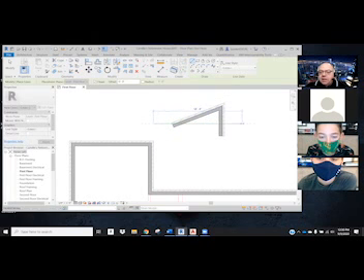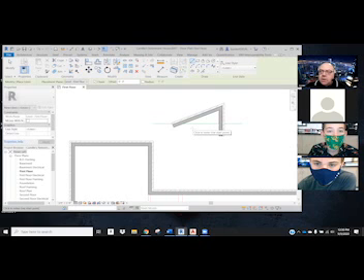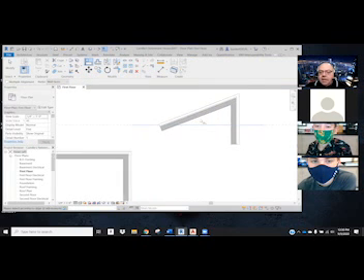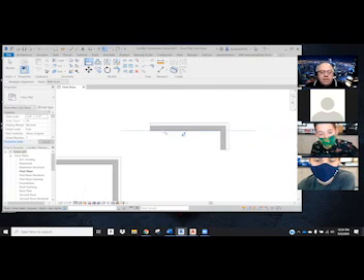I can now make sure that line is straight. And so I have that line going through. This line is always on the lowest part of your level, and so it gets covered up. So notice it's underneath my wall. Well, I can use this align tool and that model line to fix a wall, and it will straighten it out for me too. And now we got another question.